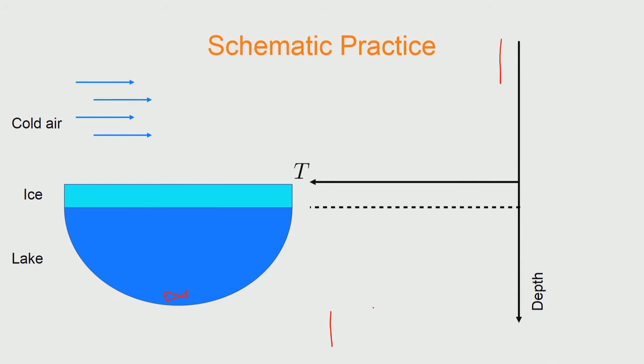Now, one temperature that we know is that the interface between the ice and the water is at 0 degrees centigrade. So, somewhere here you could draw the axis, and say that this is 0 degrees centigrade. This point we know, and then that means that the surface has to be lower than that. So, you draw like that, and immediately you can draw the profile in this manner.